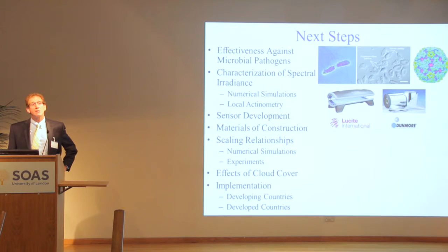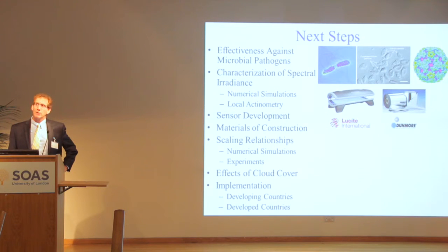The reflective material that we used on our compound parabolic collector was aluminum foil, literally, that we bought from a grocery store. It turns out to work reasonably well, but there are other materials that are more reflective of the radiation that we care about. One of those materials is called metallized plastic film, and you might be more familiar with this if you look at the inside of a potato chip bag.